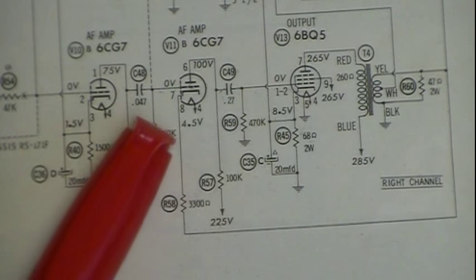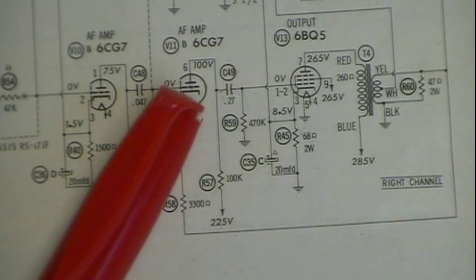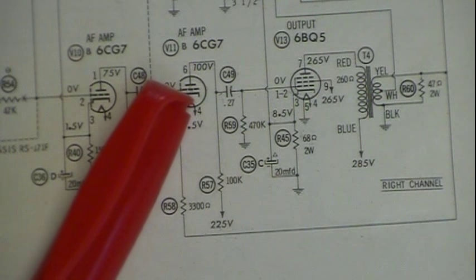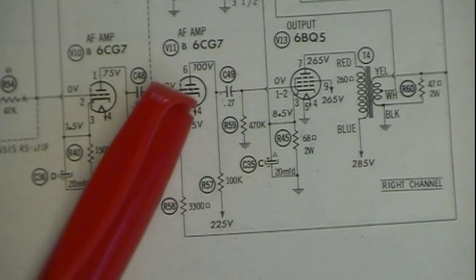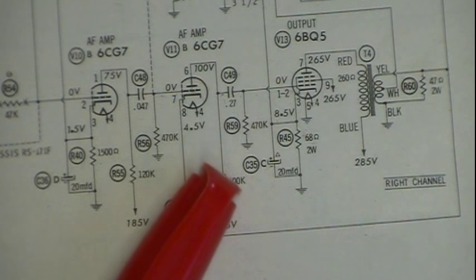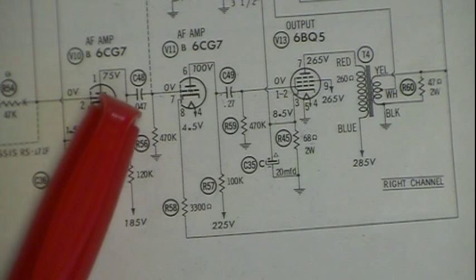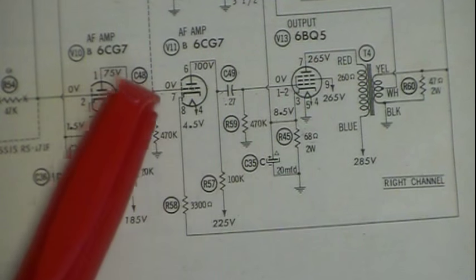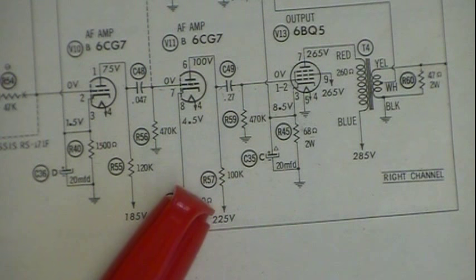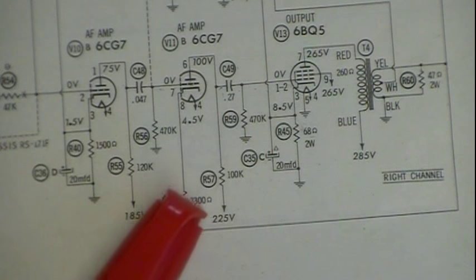They're the plate load, and if that tube starts drawing way too much current, now if it's just a little above what it should be, they would slowly burn out. But if it would spike real quick or go way high, if this tube went into full saturation, it could take out them resistors without actually burning them out. It would just take them out internally.